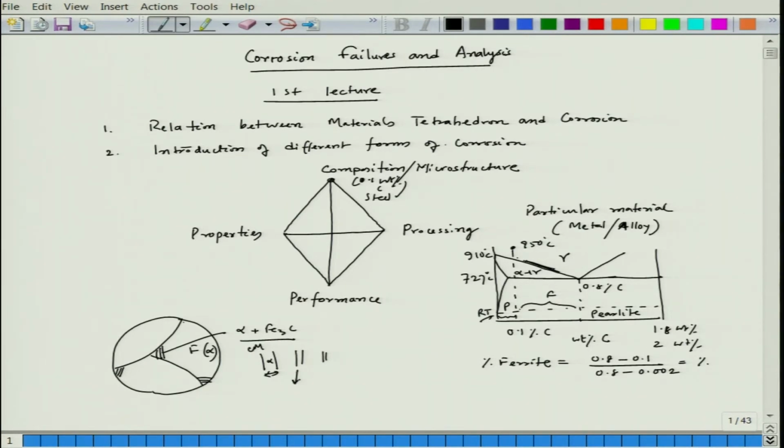So, you can say that you take the sample after doing the austenitization, you take the sample out from the furnace and leave it in the air, it cools down. So, that we call it normalized. So, this is called annealing, or we call it furnace annealing. This one we call it normalizing or air cooling,